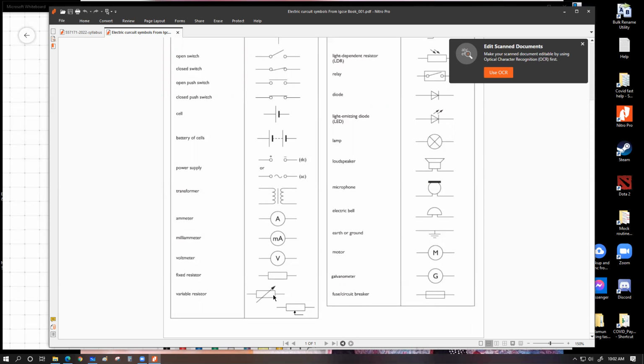The idea is very simple. This is a variable resistor, and whenever we put the fan speed to highest, we actually set the variable resistor resistance to the lowest, which means the regulator, which is basically a variable resistor, does not offer any resistance to the basic flow of current to the fan. As a result, the fan runs at its maximum speed.